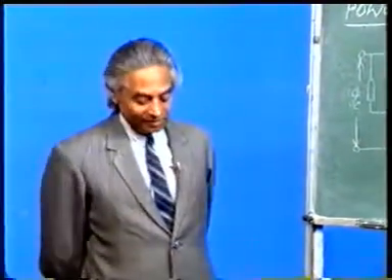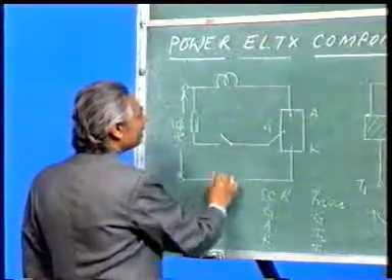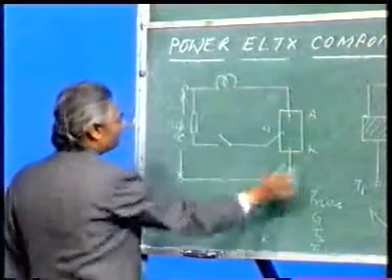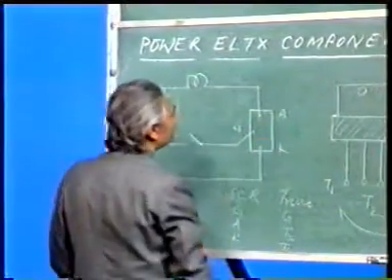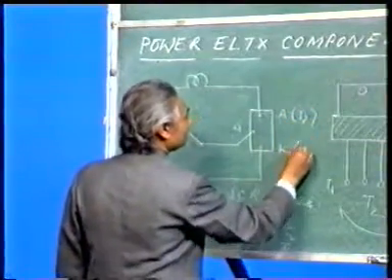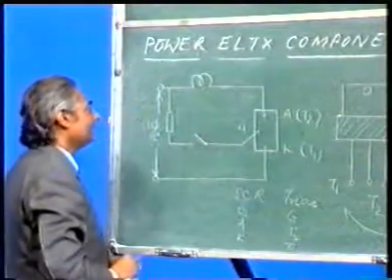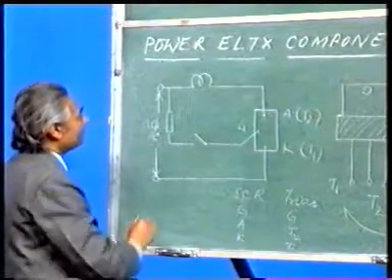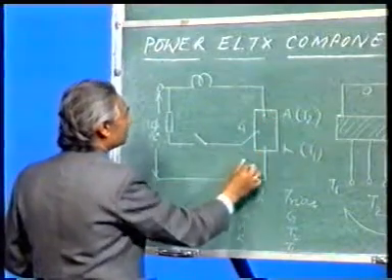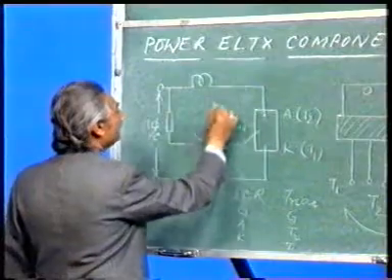Now I would also like to explain the electrical circuit which I explained in the case of SCR. The circuit is the same as I said. There is a limiting resistance here, a switch here, anode, cathode, SCR. Now I am going to replace this by a triac. So anode will be replaced by T2, cathode will be replaced by T1 and gate remains as gate. In this case also, if I give a pulse at the gate, the device should conduct and the bulb should glow. If I do not give a supply to the gate, it should not glow.